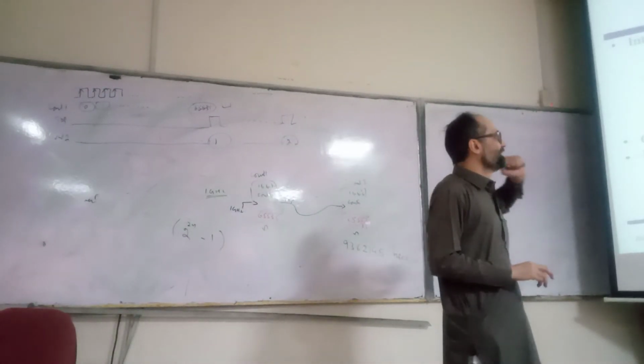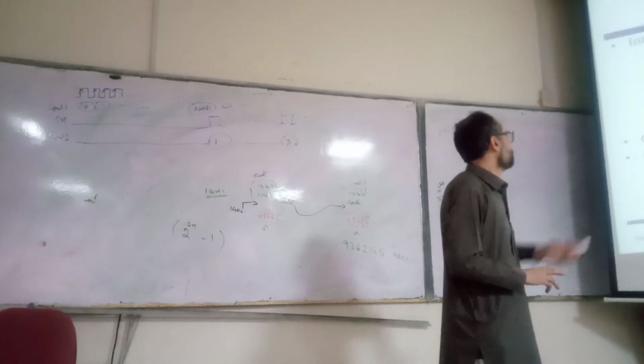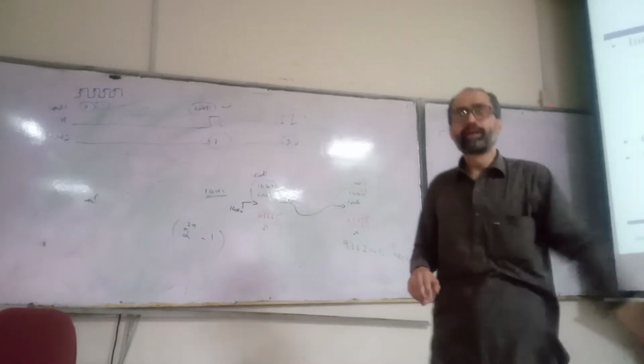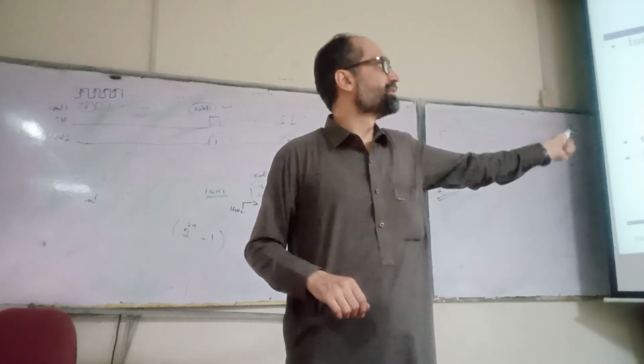Now prescaler. A prescaler is very simple. The prescaler clock divides the clock. It divides the clock, which increases the range and decreases the resolution.